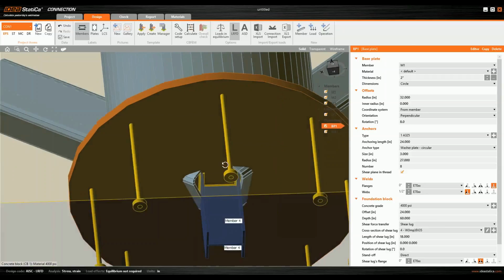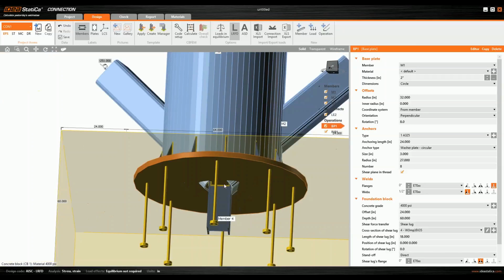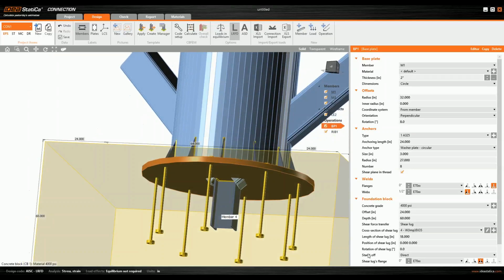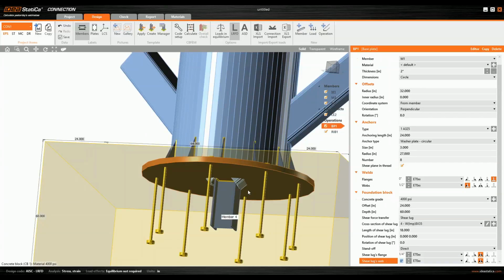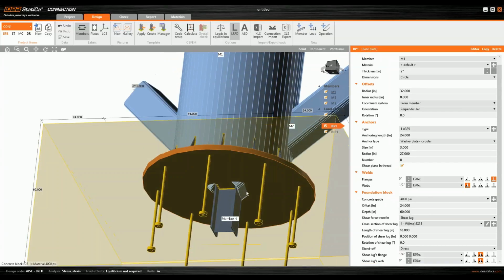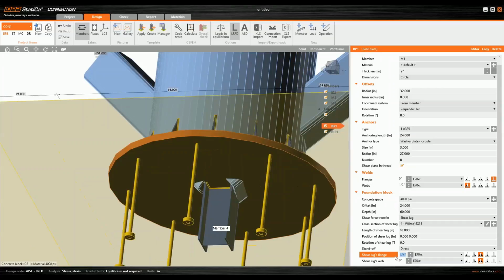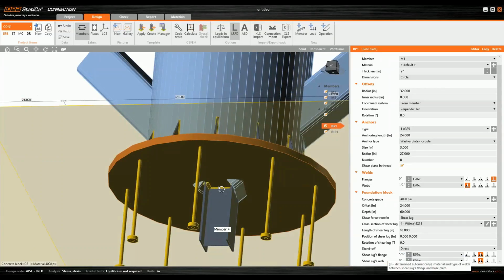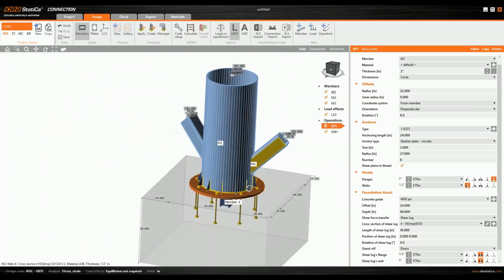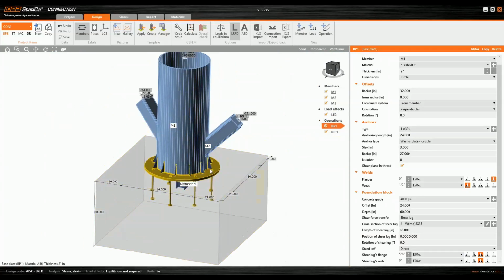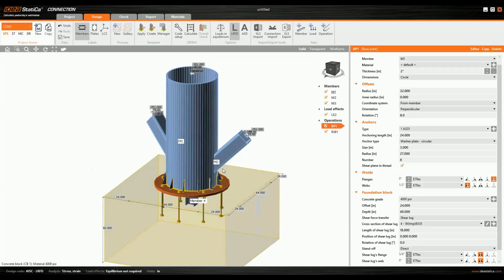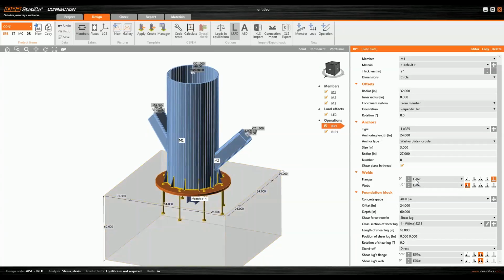And we got the welds at the default size, which we can of course change here. Let's say 1/4. That will be enough, or maybe 5 by 8. Make it a bit bigger, so you're on the safe side. You can check later on how they do after we calculate. Okay, so that's for the base plate.